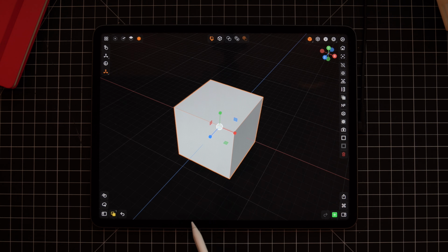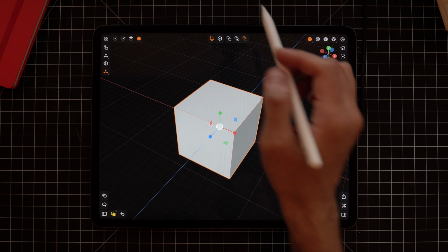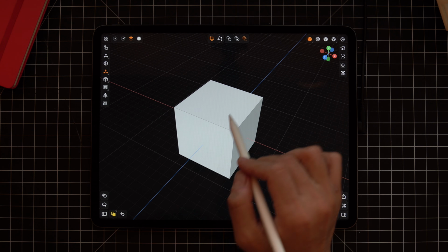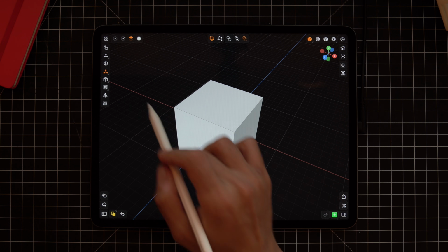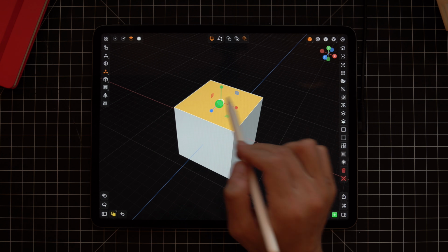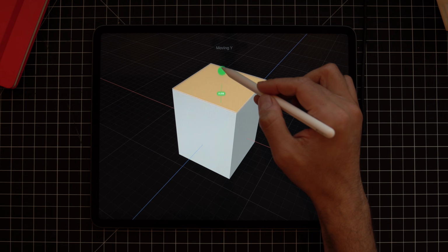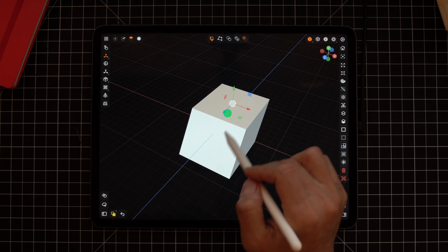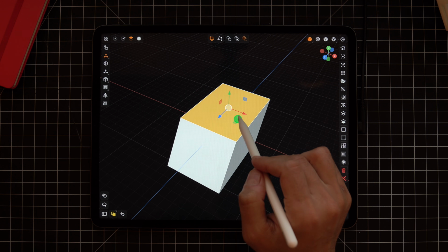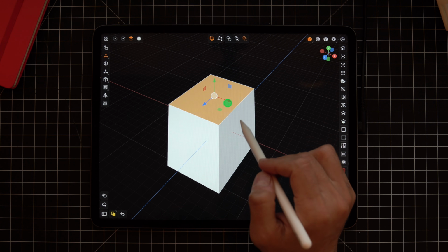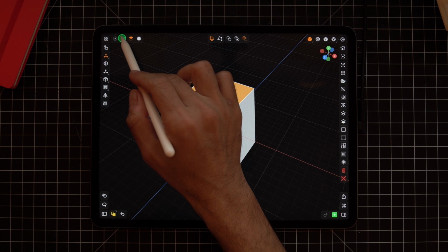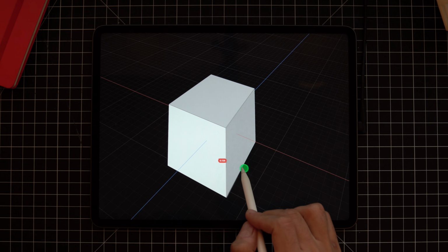So the other thing you'll probably want to do in Valence is actually move surfaces. One way to do that is to go to face selection mode, select a face, use the translate tool, and move faces. This will quickly allow you to block out things, move things, and tweak 3D models.